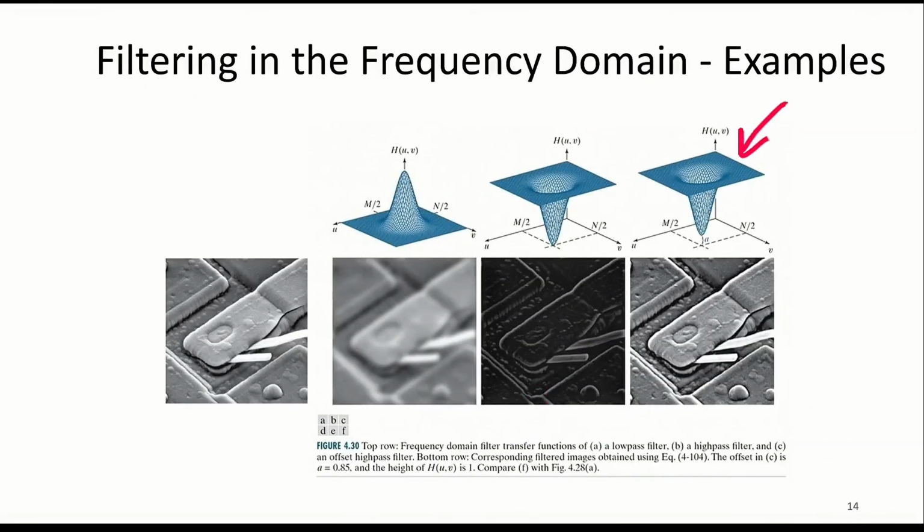Yes, okay, and convert back, I get the edges, right? And this is actually in between of this. It's a kind of a high pass filter, but here in the center it's not 0, it's lower. So what I did, I passed the high, but did not attenuate all the low frequencies, just reduced them. In this way you can see the edges are prominent and the smoothness is also there.